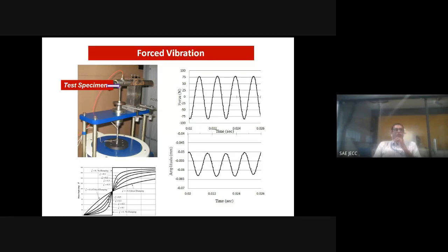We know that damped frequency, if there is damping, what will happen? It will take time to move forward. Some resistance will be offered to the system, so that the time taken will be more to complete one oscillation. Correspondingly, the 2 pi by Td, the omega d value, will be low. That means oscillations will be affected. The omega d and omega n will be different in the case of a damped vibratory system. So we discussed simply basic things, that is free vibration and forced vibration.